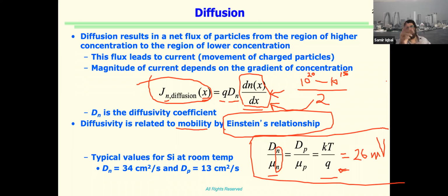Just a side note, for diffusion, one can say, okay, if you have doped a material, why would there be high concentration in one place and low concentration in the other place, right? It's the same device. So that's where you can have an excess carrier concentration maybe by shining light on one part, or maybe there may be an introduction of charge carriers using a voltage source. So there can be multiple ways you can have a very limited region with a higher spike in carrier concentration. Mostly we do it with optical materials where you shine light and there's a localized increase in carrier concentration. We call them excess charge carriers. And that's the next module.